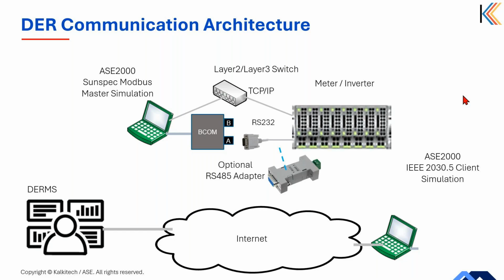Yes, there is a standard security infrastructure. It's called PKI, and generally, SunSpec certificates are issued to all the aggregators in the network, so that there is a secure channel from the aggregators to the DERMS. In some cases, site gateways can also act as an aggregator. It will be like an edge aggregator.